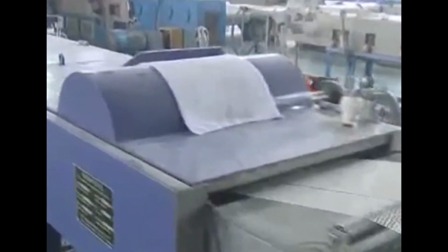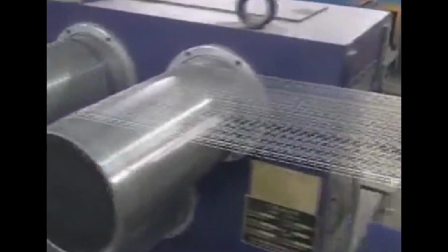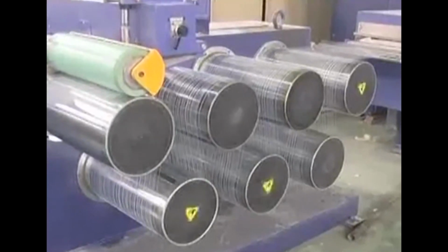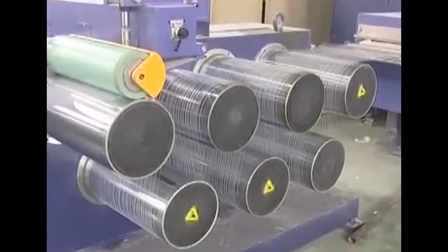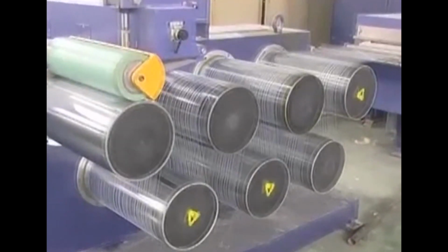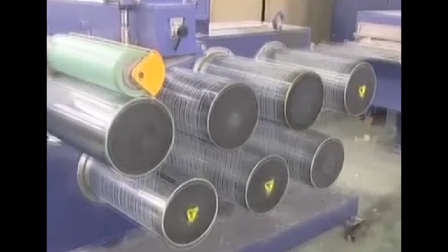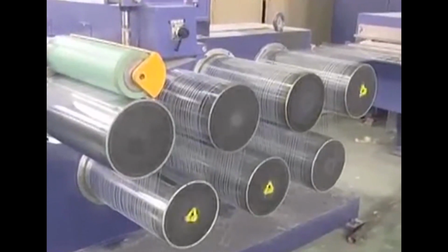And so, after melt spinning, mostly these materials are cold drawn in order to improve the fineness as well as the alignment of these molecular chains to the fiber axis. Usually, it contains two sets of rollers with a difference in speed, and the second one always revolves at a higher speed than the first one, usually maybe around 4 times higher.